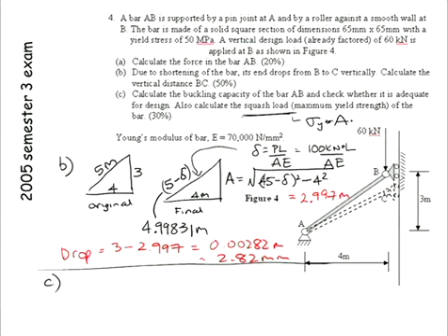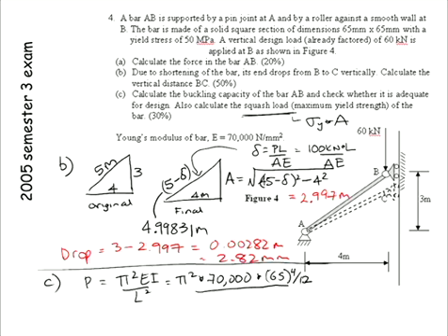So with this problem here, our section has a buckling capacity of pi squared EI on L squared, which is pi squared. We're given the Young's modulus of 70,000. Our section is a solid square section, so BD cubed on 12. And in this case here, when you come to put the length in, you can just stay with your 5 metre length. And that gives you a value of 41.1.